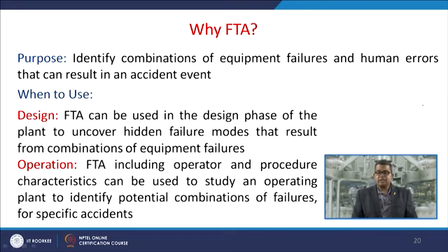Now the question arises, why fault tree analysis? Why are we looking for this fault tree analysis? The basic purpose of this fault tree analysis is to identify the combination of equipment failure and human error that can result in an accident event. So, it is a predictive mode. Now, we know why we are using this fault tree analysis, but when do we use this fault tree?